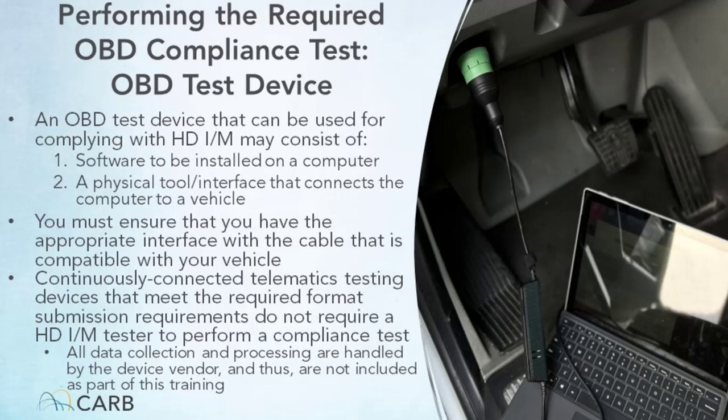OBD testing devices used to complete the OBD compliance test may vary, but in general will likely operate similar to the one shown here in this photo. Refer to the owner's manual of your testing device for specific installation and operating instructions. Not all OBD testing devices will require an HD-I&M tester to perform a compliance test.